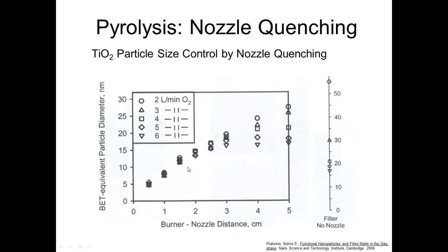So these have a tighter control range over the amount of oxygen. And again, we're getting the same particle here using less oxygen. So why would we use more oxygen and get a bigger distribution at this point? So I would change the burner design and look for a process that was rather under control.